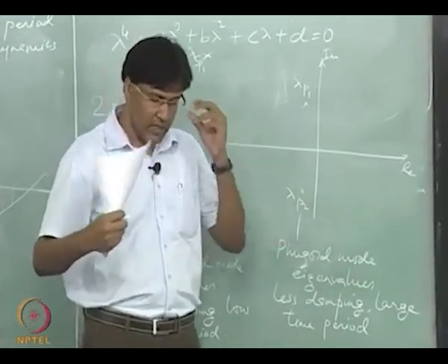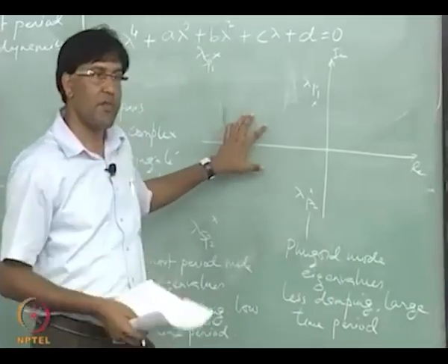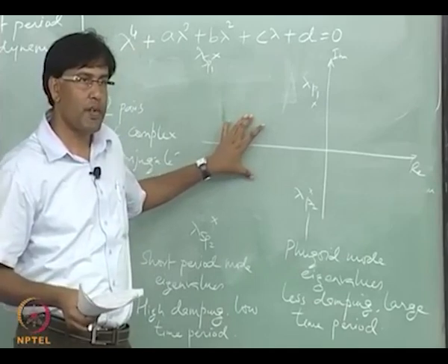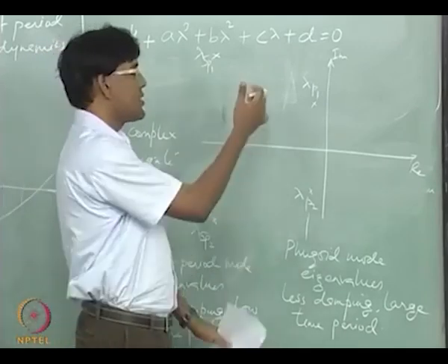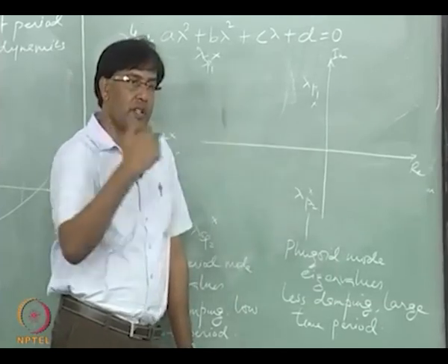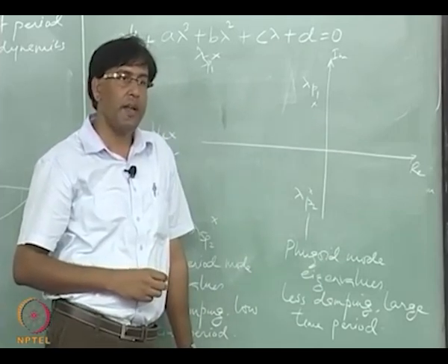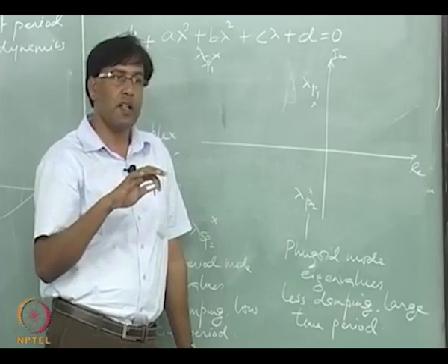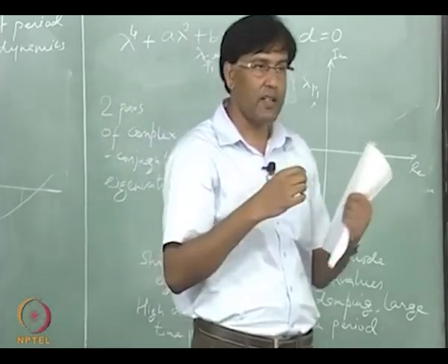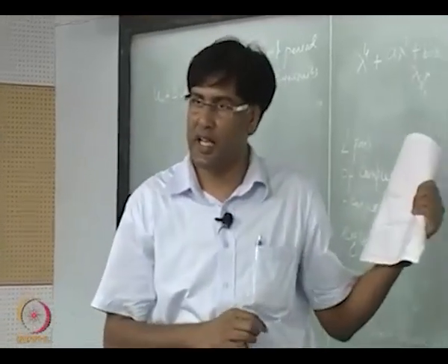right. In some cases it has been observed that they will come closer and merge with each other and then give rise to another type of dynamics. Okay, there are all kinds of things possible when you change aircraft parameters, because these eigenvalues depend upon parameters. When you change the parameters, these eigenvalues are going to move in the complex plane, right. But at low alpha flying condition, where we can relate our aircraft dynamics with some of the design parameters, that is what is our interest actually right now,